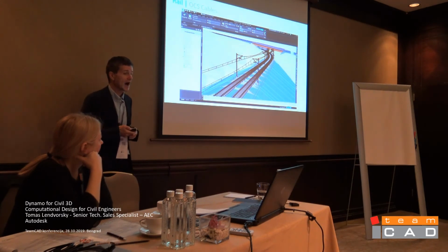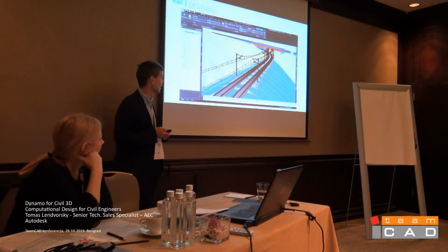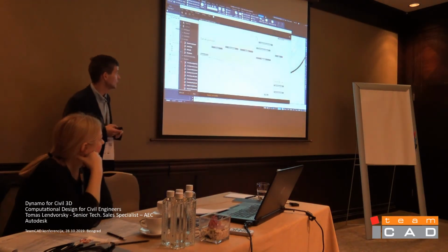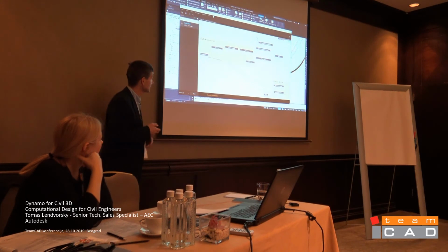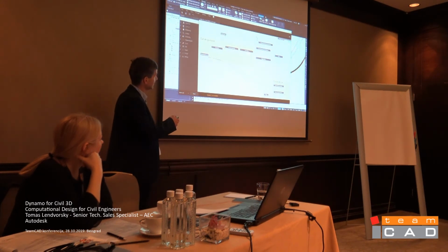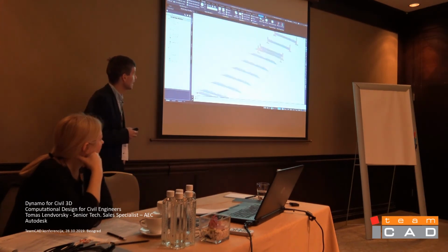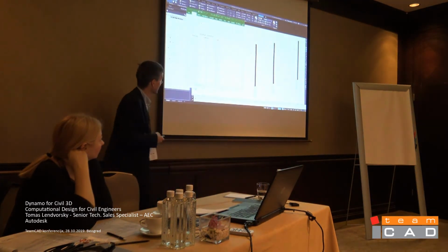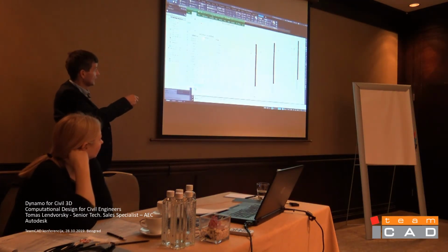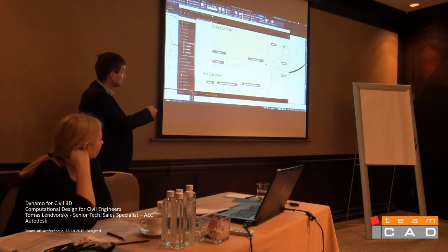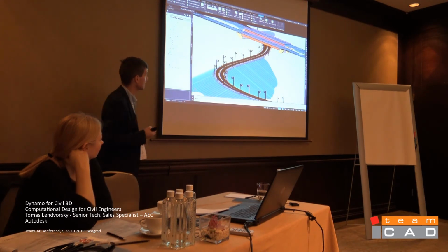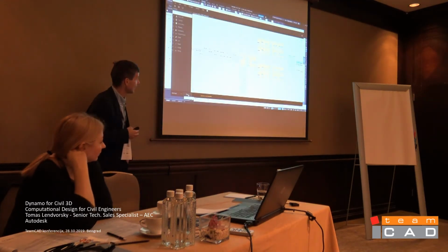So, here is the way the result can look, and here is the process. Basically, you will run the Dynamo script where you already have these different nodes connected with strings, and you can interconnect them, and then on the run, the system will create all these ties. Here is an example of the Excel sheet which you will read, because you will type your string from which you will read this information, and now you can run it along this